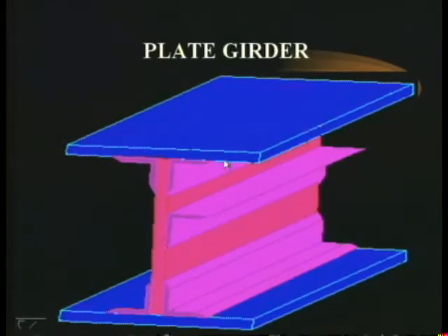We can also have a stiffener in the vertical direction. The same stiffener which is in the horizontal direction can be placed vertically, right? We didn't have it in this diagram because it may be confusing. This same member, you put it in a vertical direction, it becomes a vertical stiffener. So this horizontal stiffener, and if at all we have another member like this, a vertical stiffener, these are called intermediate stiffeners. I will repeat it for you.